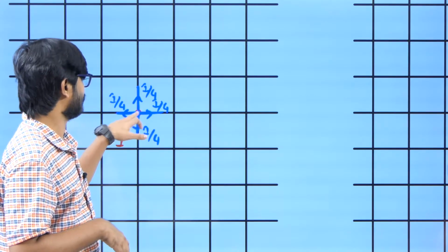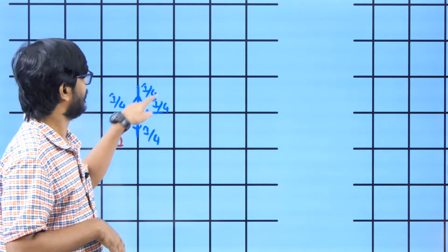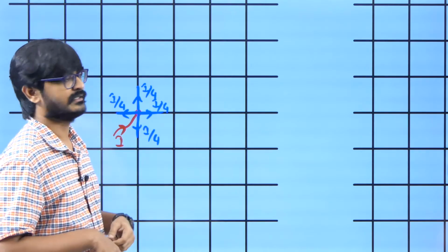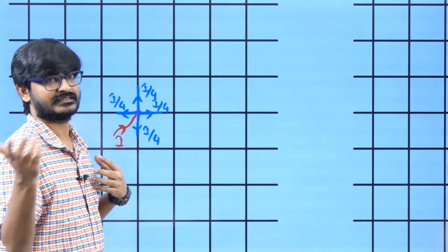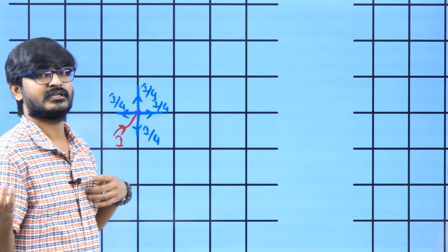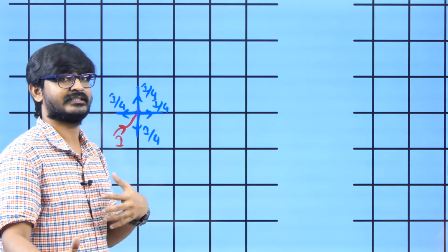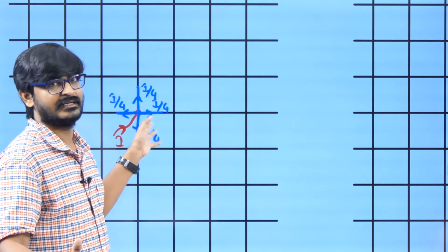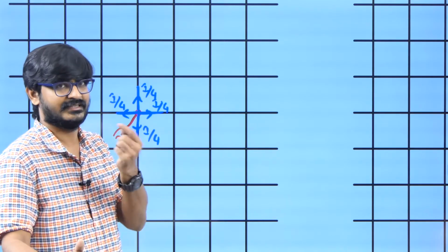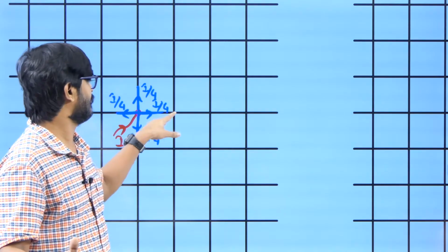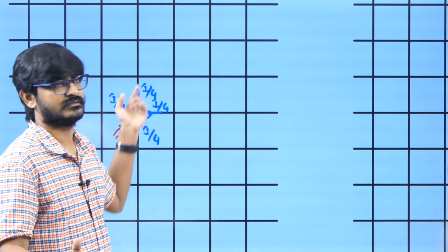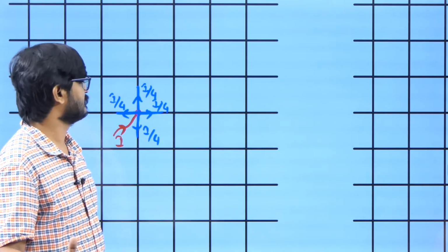Now what I am going to do here is give current I, and take equal current from every other part, which is I by the number of extra corners, right? Previously there were how many corners? Previously there were 7 extra corners. Now there are infinite extra corners. So I was taking total current by 7 out. I was giving 7I by 8, so I was taking 1 by 7th of that. So here I am giving I, I need to take 1 by infinity of that. So that is very small current, 0, right? So I will be giving I and I will be taking very small current from other nodes, right? Which is almost 0.